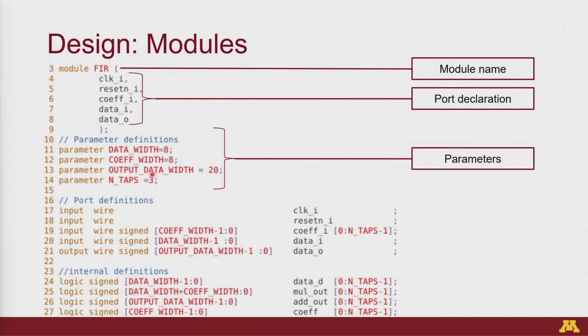As you can imagine, what is Verilog actually doing? Whenever you think of Verilog, and I'll reiterate this multiple times, you should always imagine that you're actually designing something physical. This is not meant to be some kind of coding language. It's very easy to get back into the world of Python or C++ and think everything is code which you just have to design logically.